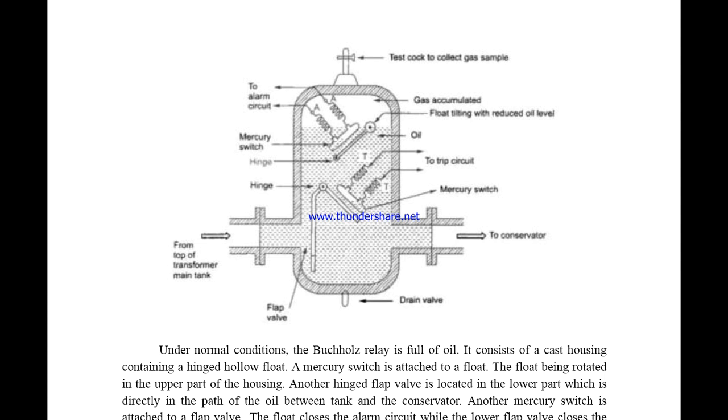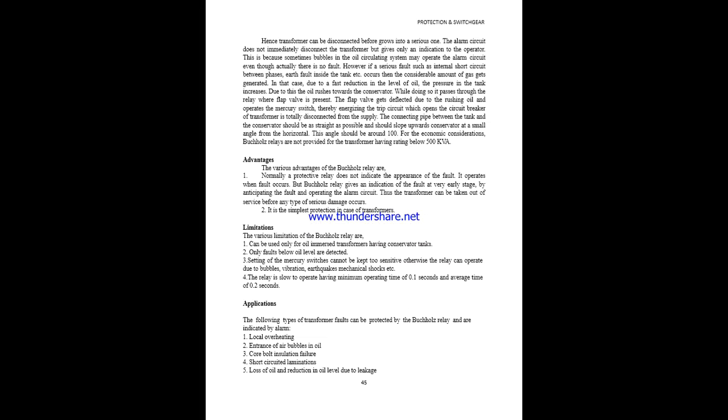But during fault conditions, the coil gets connected to the trip circuit. The flap valve will move towards the trip circuit. This will be activated to the trip circuit, and the trip circuit will open. Before that, the float tilting also closes the alarm circuit, and an alarm is sounded.